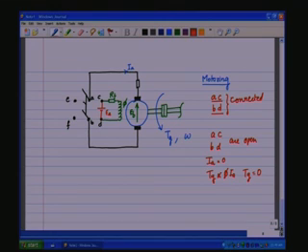Like if you are traveling in an automobile, if you switch off the engine, it will still continue to move because of the momentum, because of the inertia which is stored in the mass of the vehicle. So, we just allow it to gradually die down, there is no torque applied. So, on its own, because of the frictions associated in the bearings and so on and so forth, the shaft will coast and gradually come to 0. Now, that may take quite a long time depending upon the amount of inertia which is there on the shaft. Now, that is called coasting mode.